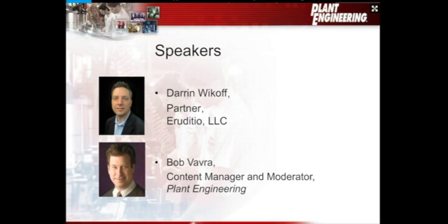If you're using a tool to help you facilitate criticality analysis, it's easier to do, because as you turn on or activate questions and answers, then the assets that you've already analyzed are flagged. I need to go back and answer these questions for those assets as well. If you're doing it in an Excel sheet, that's a little bit harder to do. But the short and sweet answer is, the resolution is first based on the number of assets in the study or in the data set, and the number of questions and answers you need should equal the square root of that data set. So you could have 10 categories and one question each as a starting point, and that's fine.